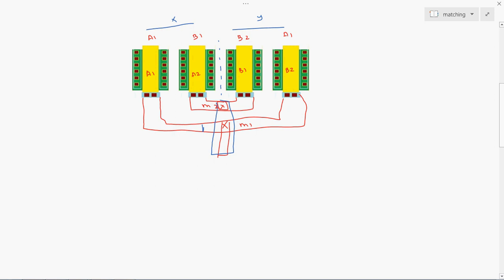The VT will change, so there is still a problem with VT. While doing the parallel routing, first I maintain equal parasitics from the A device and B device, which means the x side and y side. And also, if the patterns are shuffled and we are just rearranging the transistors, then the process variation or error introduced at fabrication time is also reduced here. This is the main reason why we go for the pattern, or why we go for matching.